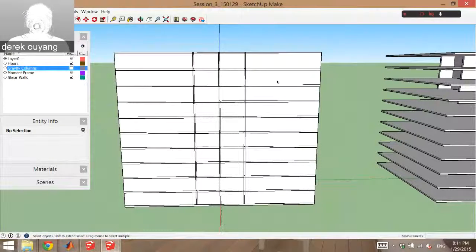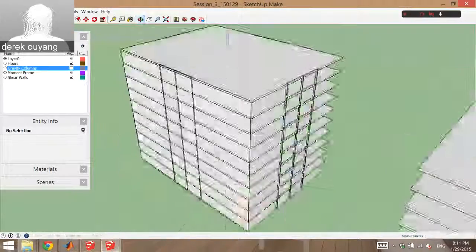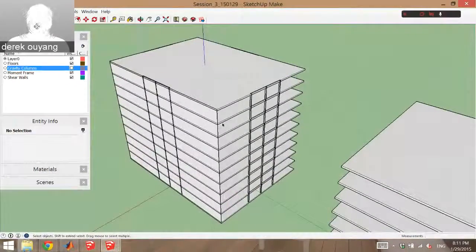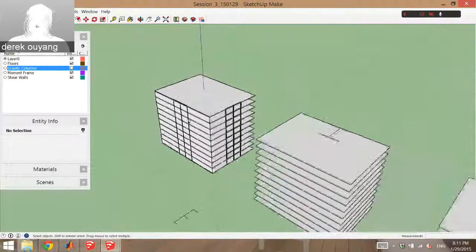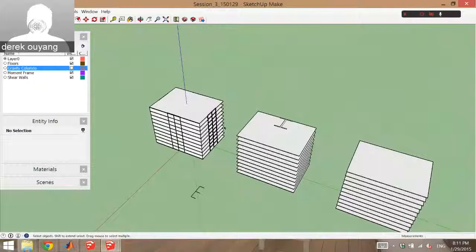So there are going to be 6 MASTAN models. Yeah, but that's in real life. If you were designing this whole building, for this assignment, just do one for each tower, one representation, right? And I'm telling you to do the worst one. You only have to do it in like one direction. Yeah, do it in the direction which would be the worst, which would be the weak axis, right?